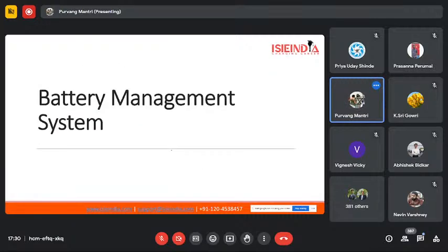So those were all the types of battery chemistries. Recently, aluminum-ion battery chemistry has come to surface, and similar to lithium-ion battery cells, aluminum-ion would use aluminum as one of its electrodes, and graphene as another electrode. And the pro of using aluminum is that it can provide more electrons compared to lithium. So it can almost provide 3 electrons per ion, and that's why it can be the future of electric battery cells.